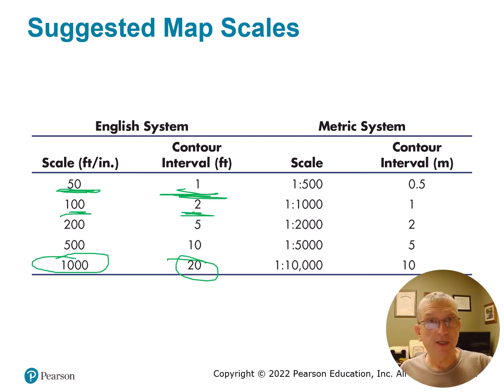If nothing else, when you meet on site, tablets are nice, but if you're zooming in and trying to pan over to a sheet, that's just not the same as unrolling a set of plans and pointing and taking a pen and making comments and marking up things with people. So always make sure that your scale accommodates what you're doing. In other words, if it's a 1 acre lot and you're putting it on a 24 by 36 sheet, don't do it at 1 inch equals 100 feet.